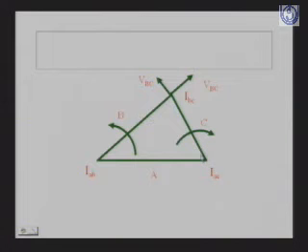Similarly, for C, since this point lies on both, the velocity direction of VBC is also perpendicular to link C. Now here you see the contradiction: the magnitude of velocity is the same for VBC, but the direction, if it exists on link B, is perpendicular to B, and if we assume it is on C, then it is perpendicular to C. So that contradicts our initial proposition.